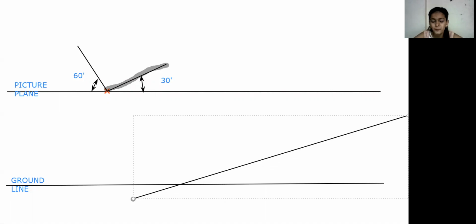So first of all, we need to draw only two lines. This is like a hint to save our time. Draw the two lines only, very light lines, at given angles or assumed angles like 30 degree and 60 degree. Then locate the observer first and draw the parallel lines to it.